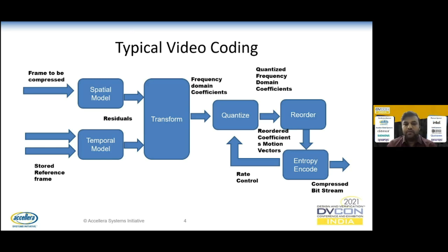For example, size, resolution, different formats such as RGB and YUV, and the frequency with which our DMA should transfer. All the different parameters which we enable or disable during the test content generation determine the performance of our media. So we end up tweaking a lot of IP level configurations, which are defined parameters. Due to the requirements that come up, we have to tweak those options to see the performance validations with and without a specific IP block.